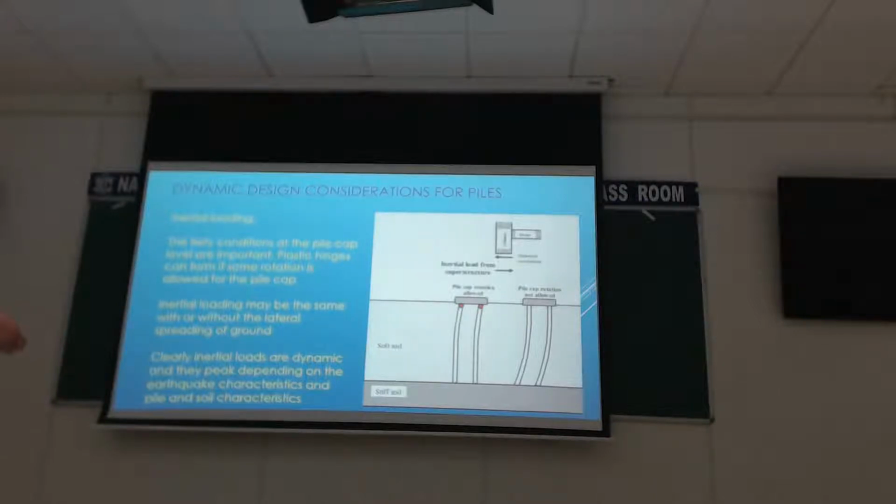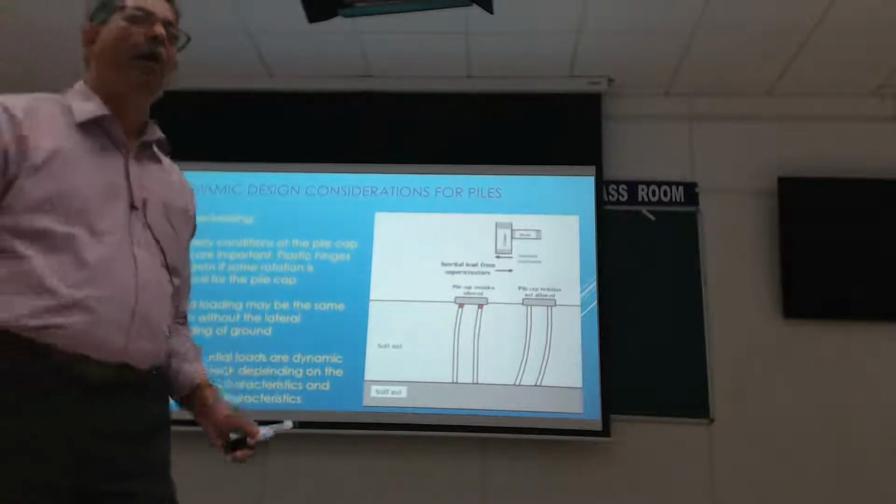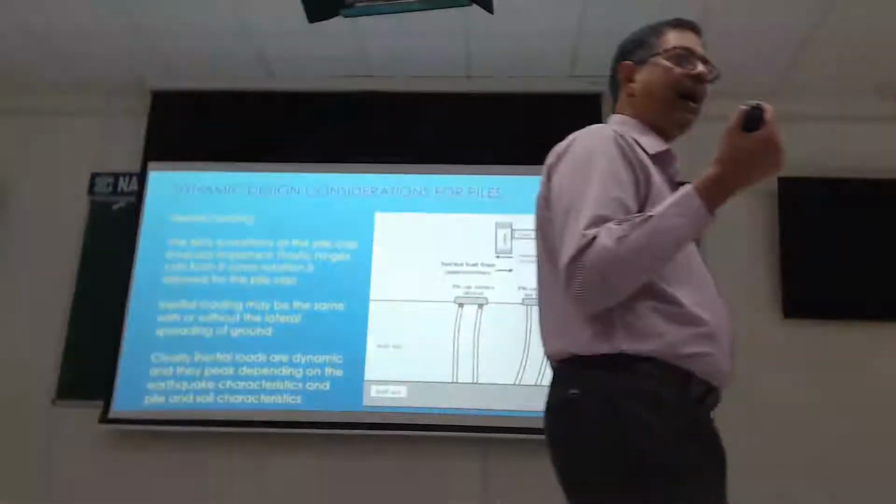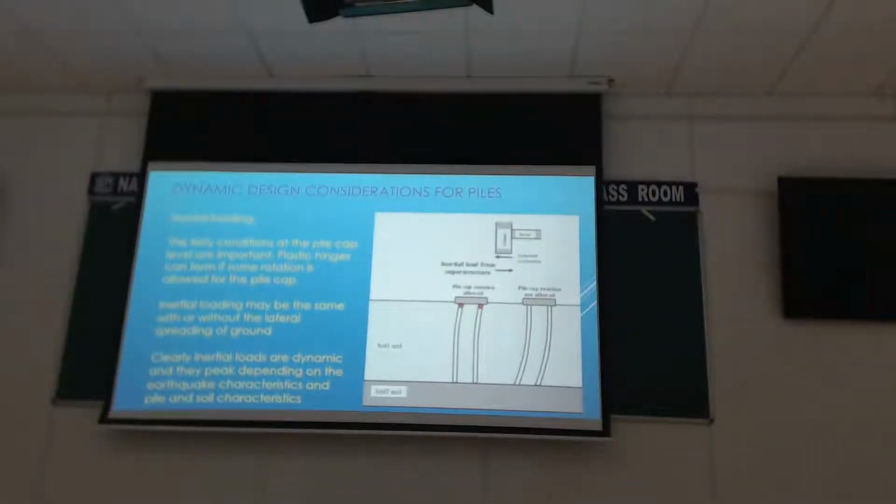Obviously, if you are designing for this case, you need reinforcement here because it is bending that way. Whereas if it does that, it's bending the other way. Completely different mechanisms on one simple thing. And I don't even need to do any tests to identify this. This is just me sitting down and imagining. Yeah, makes sense?